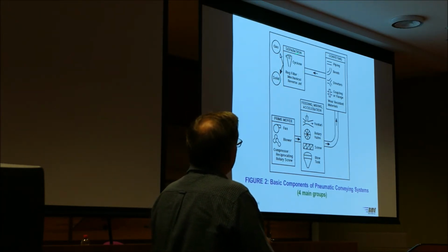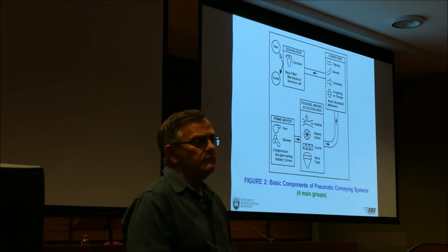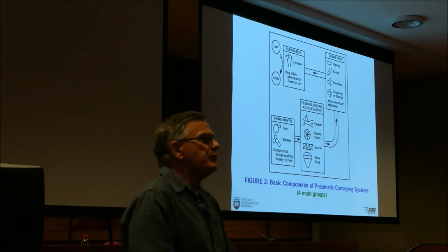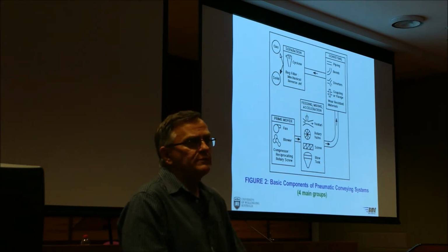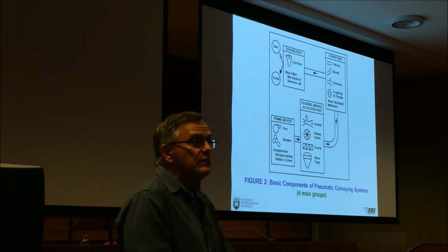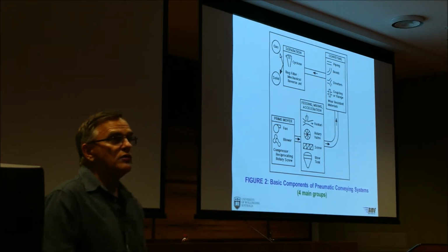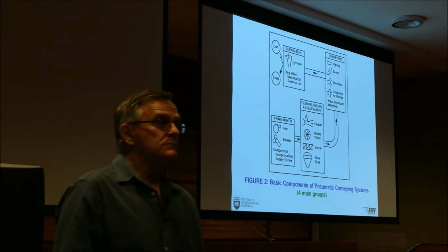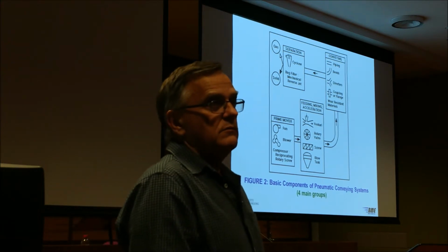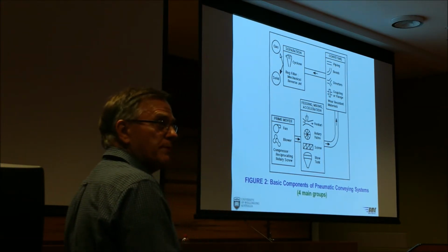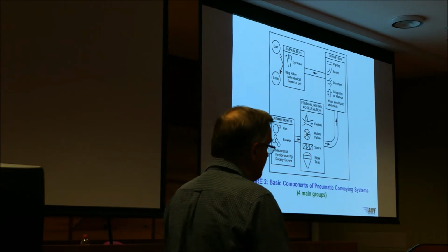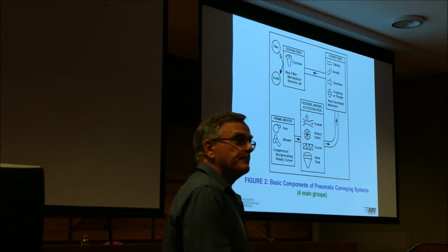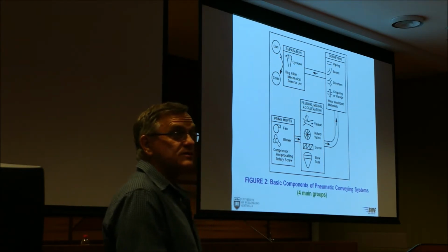But whatever device you pick here, there's nothing 100%. Filters will get you to 99.99 or something like that, that sort of percentage. It's still not 100%. So if you're pneumatically conveying arsenic powder, of course you can't allow any submicron particles to get out in the atmosphere or workplace. It's logical. It's a poisonous substance.